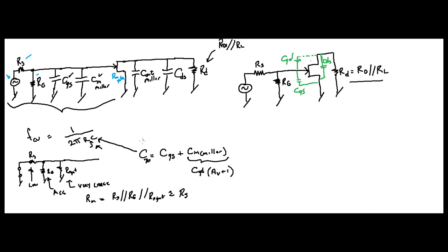As you can see, this input capacitance is simply multiplied by that gain, and gain is usually a larger number, so this has an effect. This is an important calculation, so make sure you think about it. It should be larger, because if your gain's 200 or something like that, it's 200 times that value, which gives you a larger capacitance.